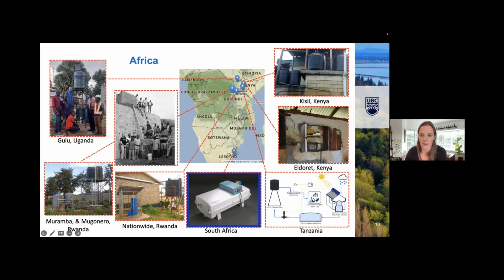The one mentioned in the lower right, this is in Tanzania, and this was submitted by the University of Toronto, Carly Wong and Ron Hoffman, and they were working in collaboration with WaterAid Tanzania. But here, these systems were operated at 6 different healthcare facilities around Tanzania. And you can see in the schematic, they had an elevated tank going through a UV device. Basically, they were collecting water from rainwater and running it through a first flush or a washout chamber, and then storing the treated water in an underground tank prior to use.